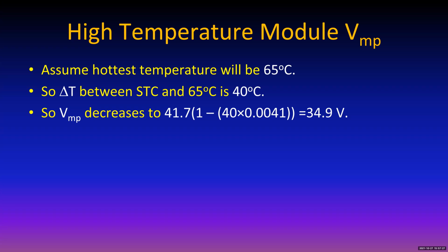And that's what these nice black PV modules do. They convert 20% to electricity. They reflect some of it away, and about 75% of it gets converted into heat. So, of course, then half of that heat radiates upward, half radiates downward.